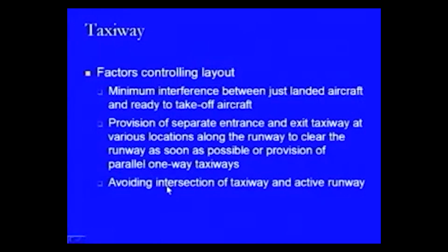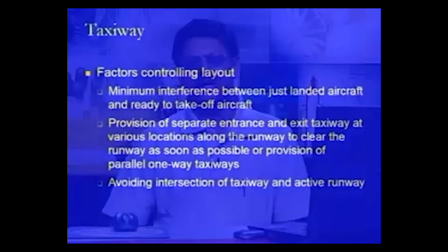Another important thing at the time of fixing the layout of the taxiways within the overall airport space is that there should not be any intersection of a taxiway with the active runway. The reason behind this is that these two components have different speed conditions. The active runway has a much higher speed, whereas on the taxiways the speed of the aircraft is quite low.